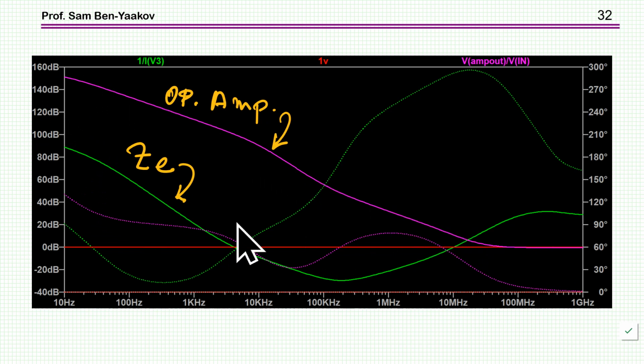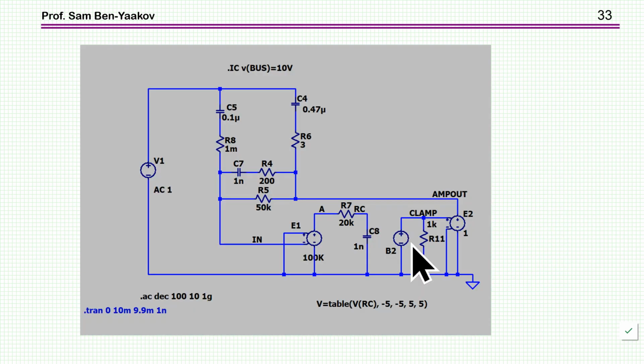This is of course the amplitude. This is the phase, which I'm not interested in. And we see that indeed this is high bandwidth, well, 10 megahertz, 200, but then the behavior is kind of strange. I've put here a 0 dB line, so it sort of converges to this, and the gain is just not good enough. So what I did, I just built my own amplifier.